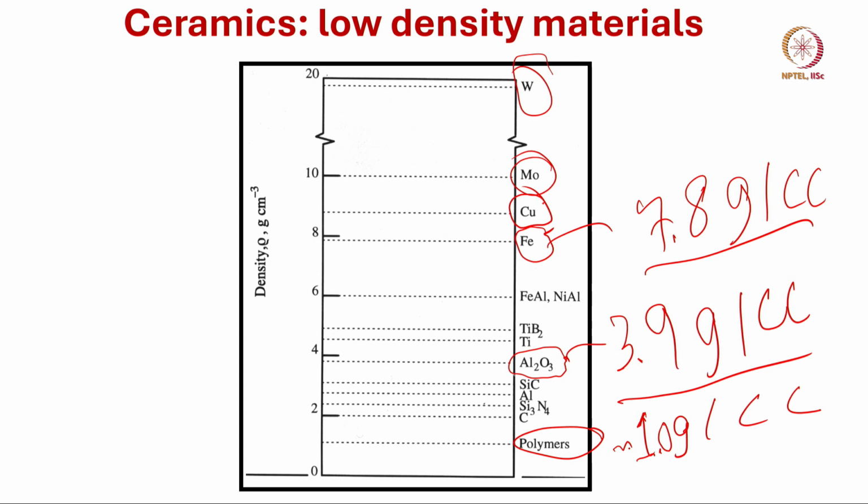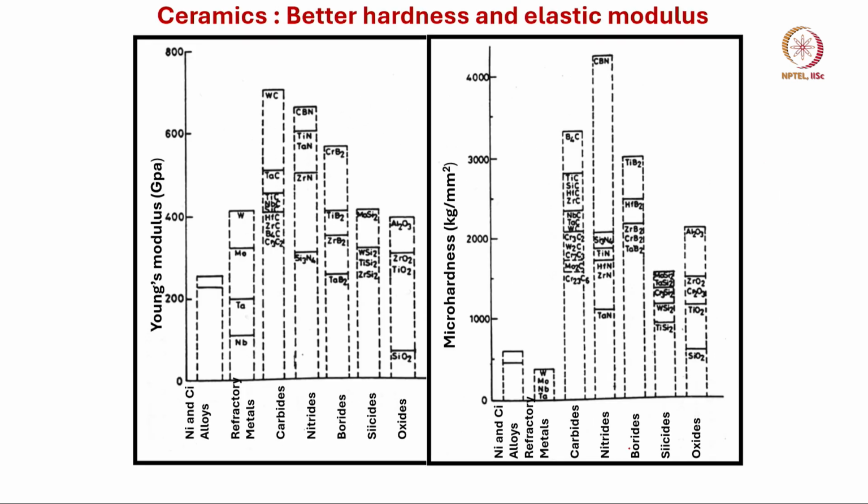So, again, if you take an engineering component of a certain volume and compare it with a polymeric component of similar design, shape and identical volume to the steel counterpart, the polymeric component will weigh 1/8 that of the steel. So, this example shows you how important density is.